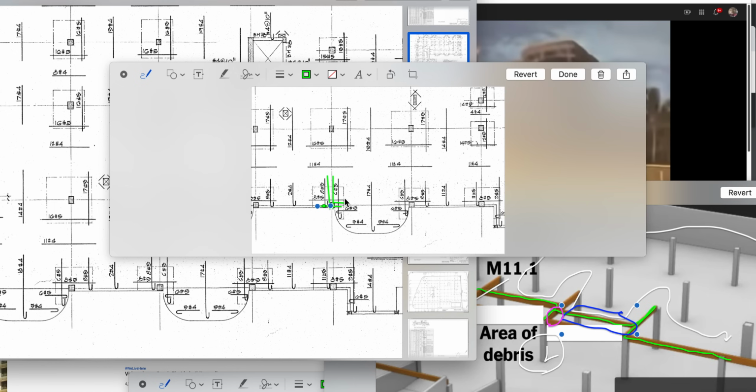It's only 3,000 psi concrete. It does that spalling action I talk about, where I show the lever action, where I say that it's holding the deck. In this case, the deck is going down. The rebar stays inside here for the most part, and it just pries off the top layer here.